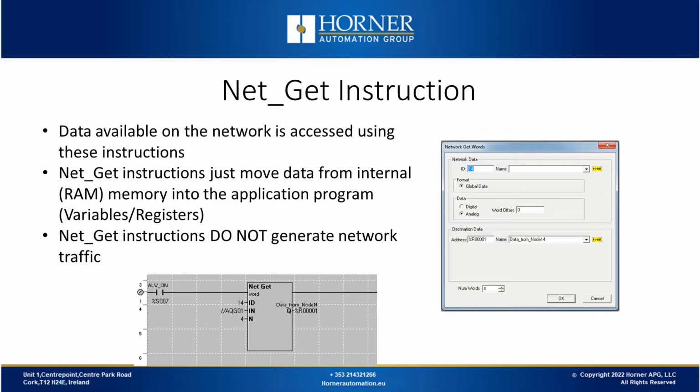Next, we have the NetGet instruction, and that is basically a data move where it grabs data internally from RAM and it's going to place it like a move block would into an internal variable. Again, NetGet instructions do not generate network traffic because they're just a copy from local memory.